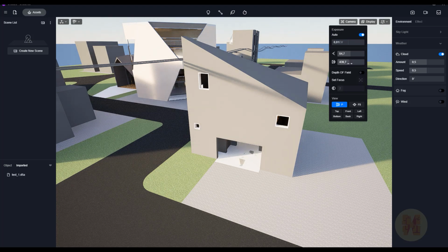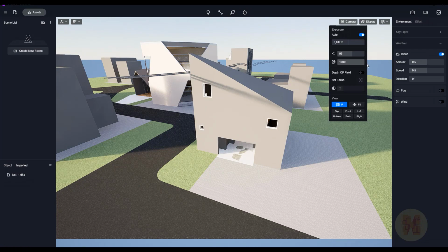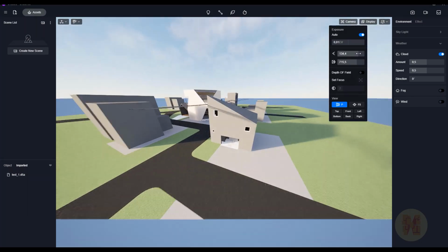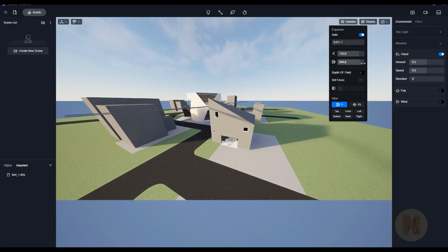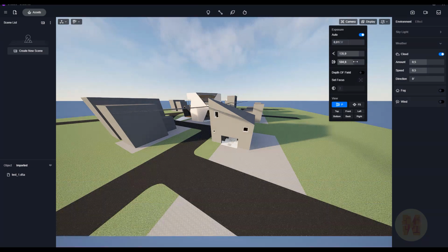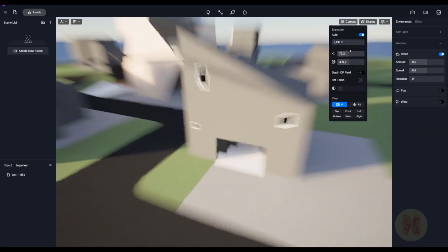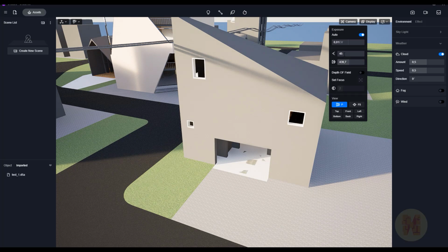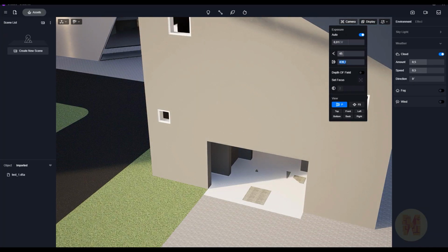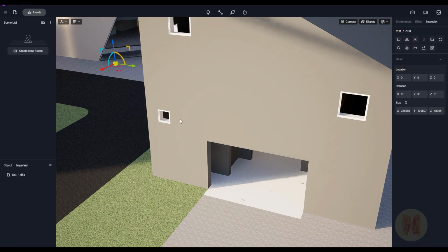And the clip, this I really like. For example, if you are doing your view with the really close angle like this, you can manipulate the cutting of your view. This is a really nice thing. I will change it to 45. This is more preferred for me, and here it will be 0. I don't need to cut anything.